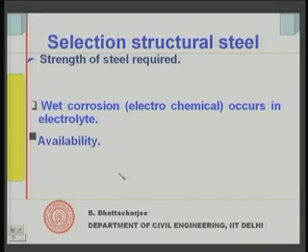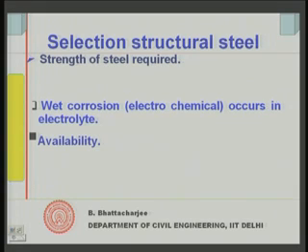We have to see, because steel, iron will always corrode; thermodynamically it will always tend to form oxide. So, we will have to see that the environment, the exposure condition, is very, very important. Exposure condition is important, availability is important, ductility and other mechanical properties are also equally important. Strength and other mechanical properties, availability, exposure condition,